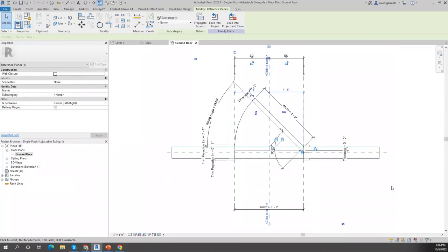By the way, Revit out of the box has a whole bunch of given family templates. When you're going to start to create a family, start from one of the pre-made templates, or make sure that you start from the correct template. That is very important.